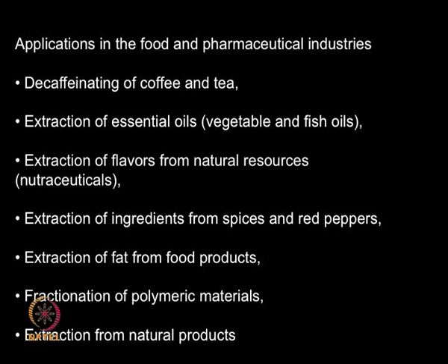We can use it for fractionating polymeric materials. We can separate out polymers based on its molecular weights. So if one is interested in separating out polymeric materials, more natural polymers as well as synthetic polymers based on molecular weight, low molecular weight content and higher molecular weight content polymeric material, then supercritical fluid extraction is a very good approach for that.